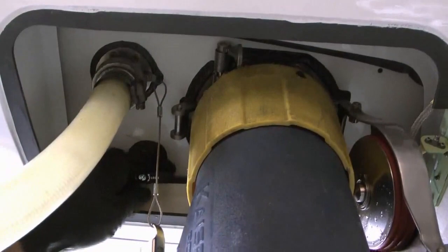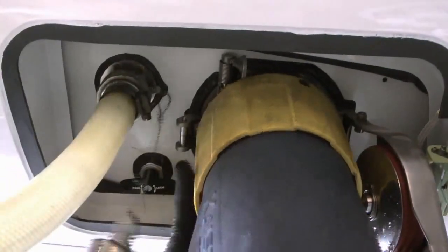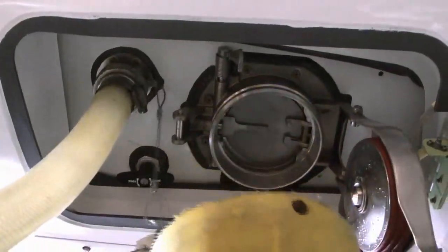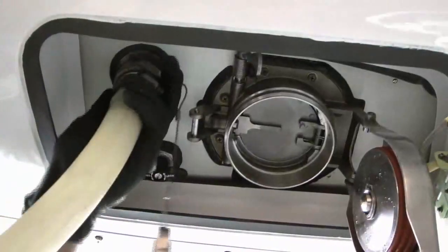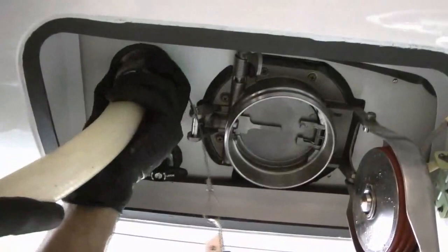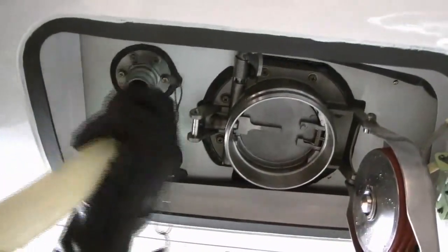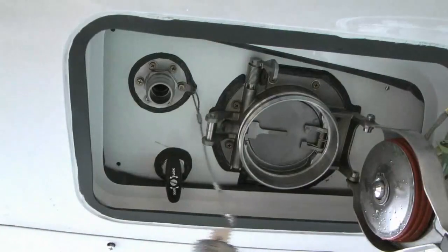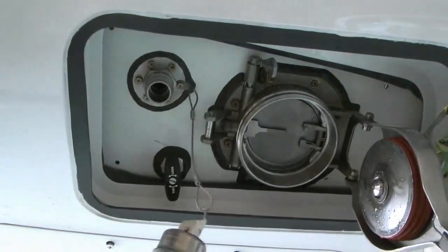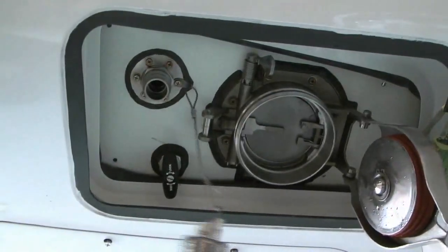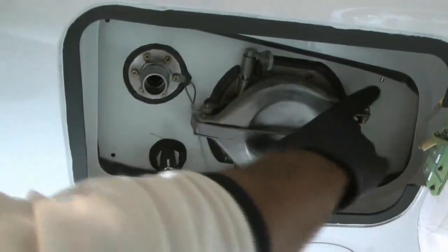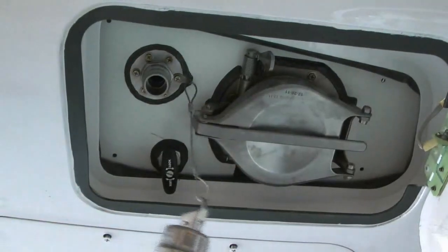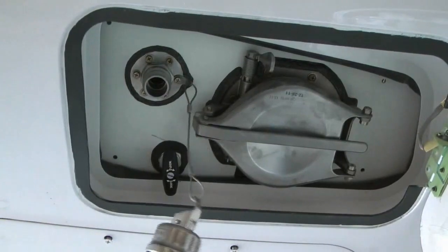Unlock and push the T-handle in after all liquid is drained. Disconnect the lavatory dumping coupling from the RTS servicing panel drain valve. Disconnect the lavatory filling coupling from the RTS rinse valve. Close the cap of the RTS service panel drain valve and latch the lever. The flapper valve closes automatically when the cap is closed.